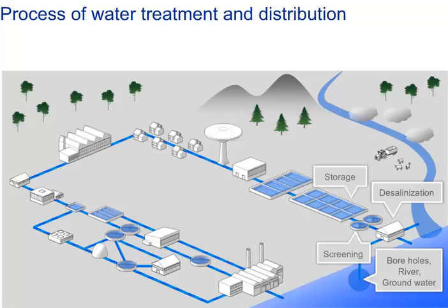Storage. Water from rivers may also be stored in bankside reservoirs for periods between a few days and many months to allow natural biological purification to take place. This is especially important if treatment is by slow sand filters. Storage reservoirs also provide a buffer against short periods of drought, or to allow water supply to be maintained during transitory pollution incidents in the source river.